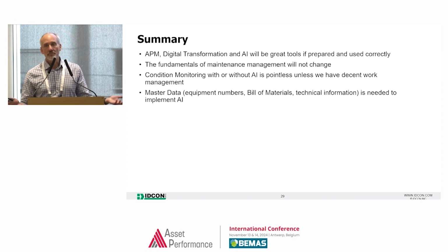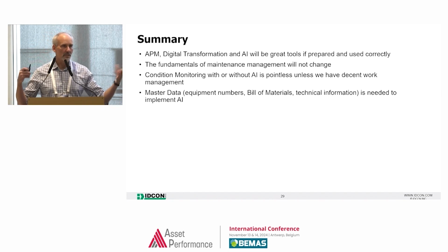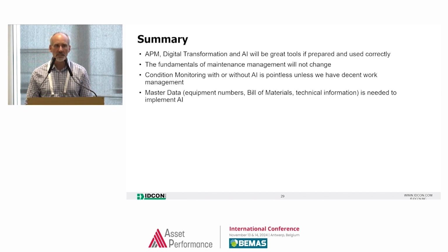Master data obviously has to be right. Everybody says that, right? Whoever you talk to. You can't just have pump. You have to actually know, well, what kind of coupling is it? Because a gear coupling has a different failure mode than a tire coupling. They're different. Or a jaw coupling, they fail differently. You need to know what kind of seal. Is it a packing or mechanical seal? I need to know. If I don't have that data, forget about digital transformation. So my advice is to start working on it because somebody's going to ask you to do it sooner or later, so you might as well clean up your data.